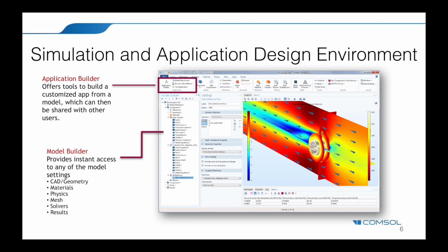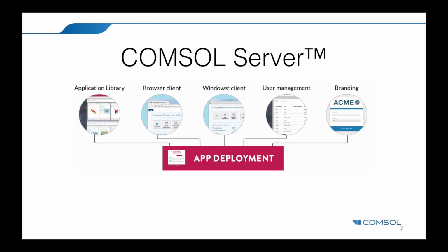Because, as I mentioned earlier, once you are finished with a simulation, you may want to be able to share the results with a colleague or a customer without sharing your entire model. The application builder will let you build this user interface around your simulation. Then, to share it with someone who doesn't have COMSOL installed on their machine, you would use a local installation of the COMSOL Server, which makes the app accessible either through a COMSOL client or a web browser.